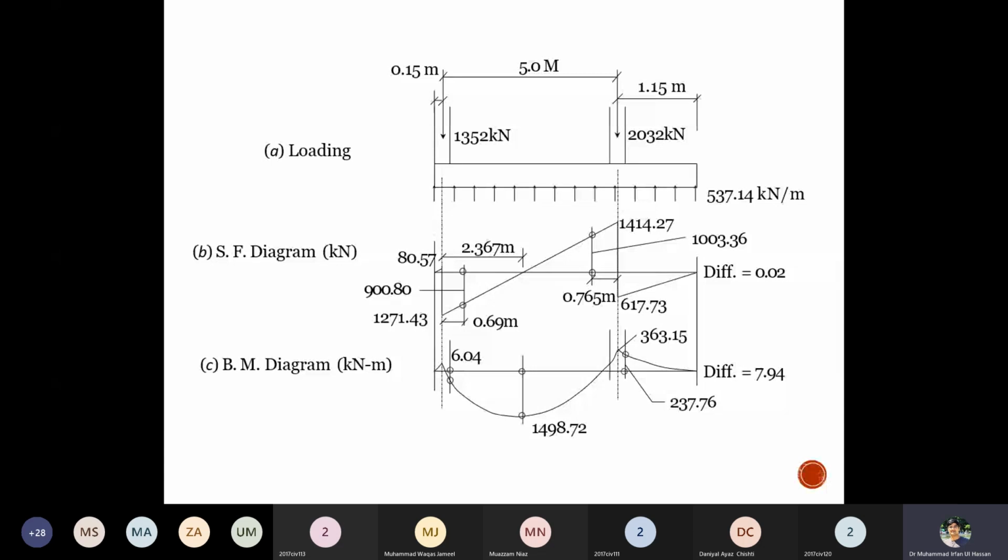You know that the moment is maximum where the shear is zero. And the shear is maximum at the supports, at the face of the support, where the shear is critical at a distance d from the face of the support. One-way shear. This is a one-way shear diagram. The shear force is basically telling us about the one-way shear because we have plotted this shear force diagram in one direction. We are not taking it as punching.